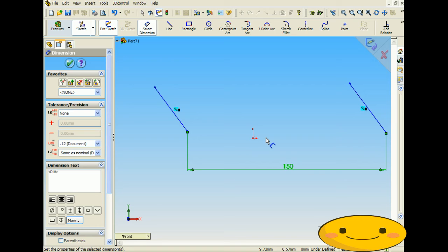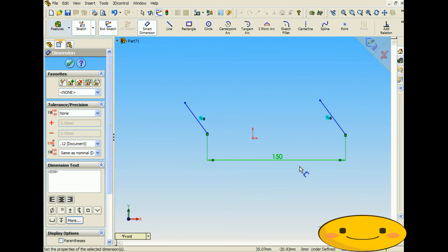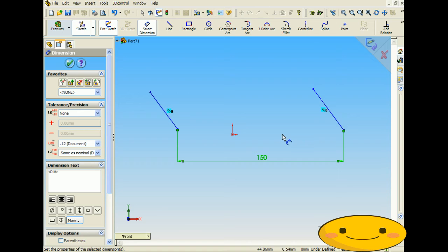They're on the same line, so they're just kind of like a distance of 0, but this line's able to move up and down. So that's the difference between using a parallel and a collinear relation. So with the parallel, you're able to have a distance in between the two like that, and a distance like that. Whereas with the collinear, it's only a distance up and down, not side to side.